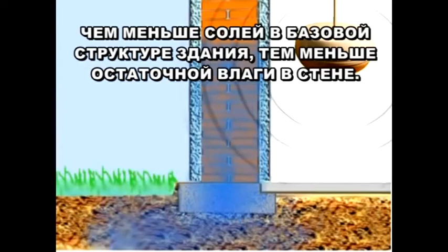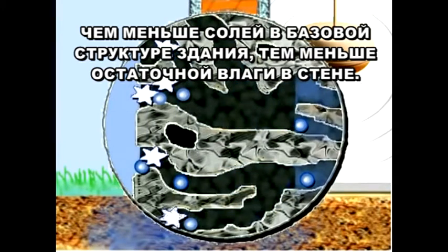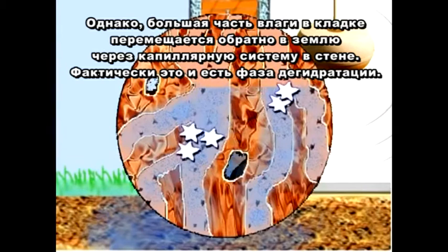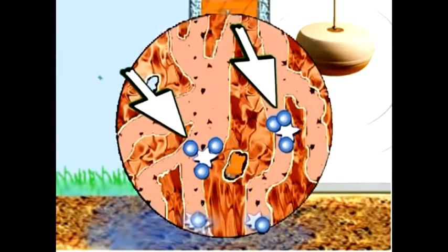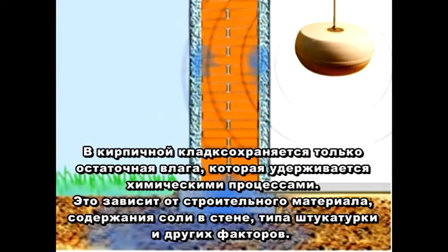The fewer salts there are in the basic structure of the building, the less residual moisture remains in the wall. However, a large part of the masonry moisture moves back into the ground through the capillary system in the wall, which is the actual phase of dehumidification. What remains is the chemically bound residual moisture in masonry.